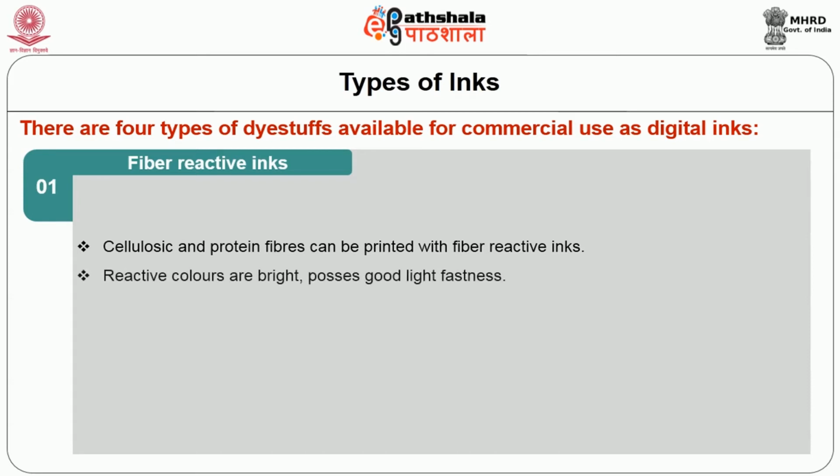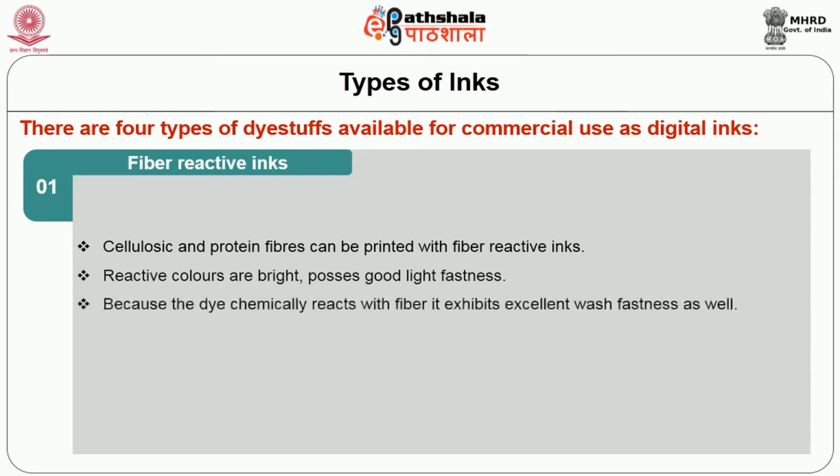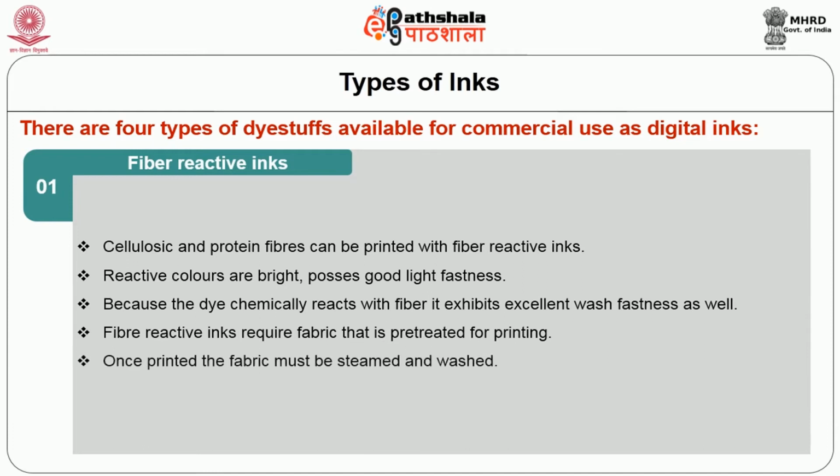Reactive colors are bright, possess good light fastness. Because the dye chemically reacts with the fiber, it exhibits excellent wash fastness as well. Fiber reactive inks require fabrics that are pre-treated for printing. Once printed, the fabric must be steamed and washed.